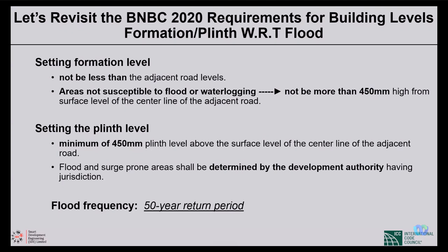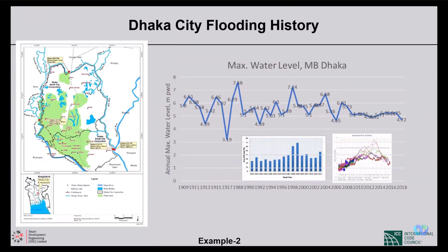Flood frequency is important, as we already talked about, for the level we want to fix: the plinth level and formation level, which we have to fix based on the code suggested in BNBC. Where you have a problem of flood areas or drainage location, you have to do the flood analysis. How can you do that? That we're going to show you.